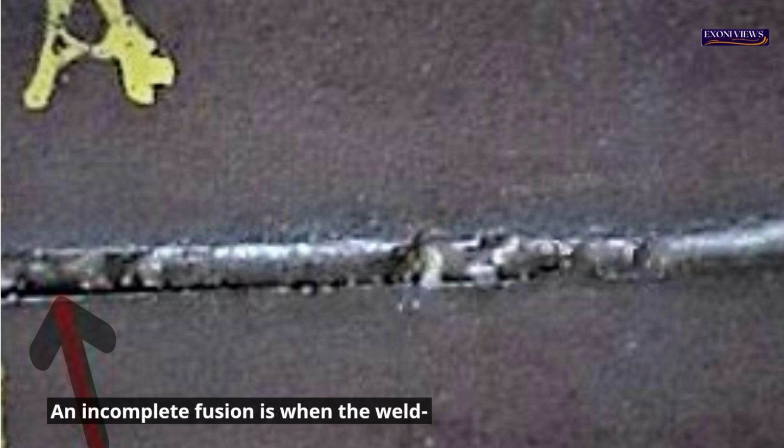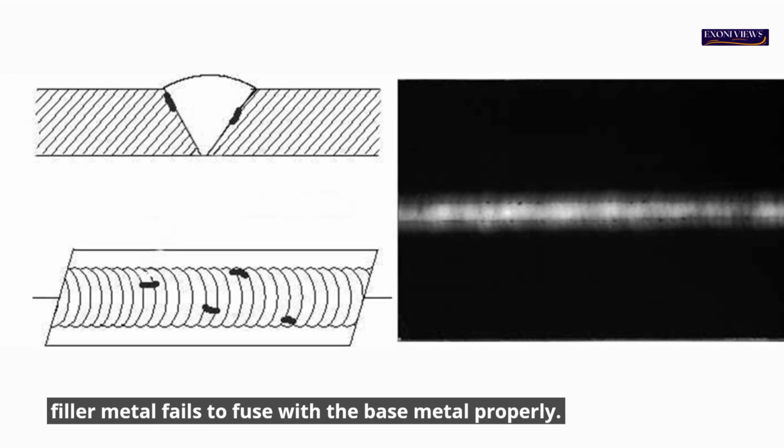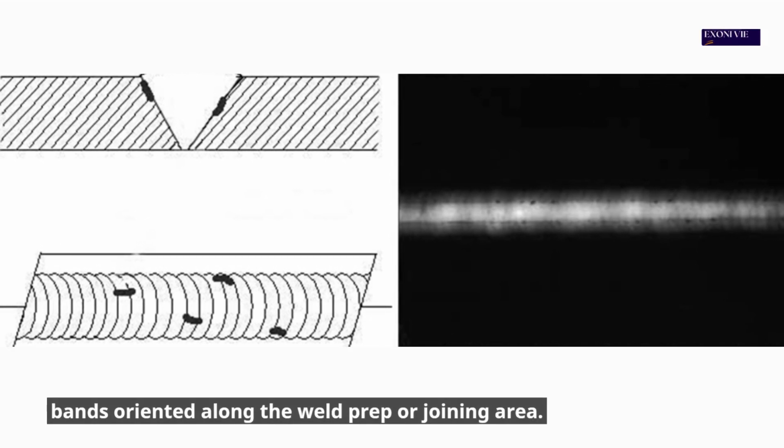Incomplete fusion. An incomplete fusion is when the weld filler metal fails to fuse with the base metal properly. The situation is usually visible on radiographs as a dark band or bands oriented along the weld prep or joining area.